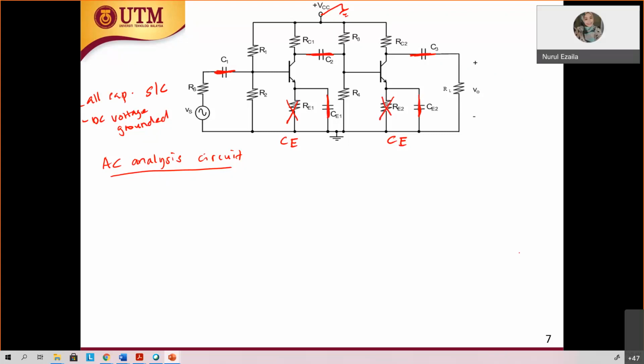All right, let's do it. Common emitter and common emitter. First thing, you know that when you have common emitter, you have R pi. Your ground is the emitter, your base is at the input, and don't forget you have your gm V pi. This is your collector. Don't forget that you have V pi over here. Why is my R down there?